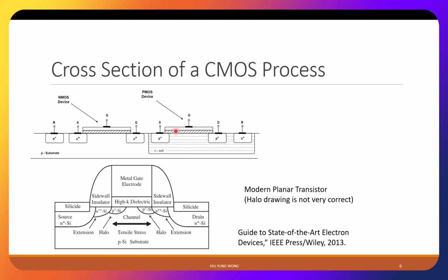I said just now, right? So this is a typical CMOS. This is the old one, right? Pretty old CMOS. You have a substrate, which is P-type, mostly hole. Then on top of it, you form the NMOS. Then you have an N-type source and drain and P-type substrate. You also need to connect the P-type substrate to a contact, otherwise it will be floating.